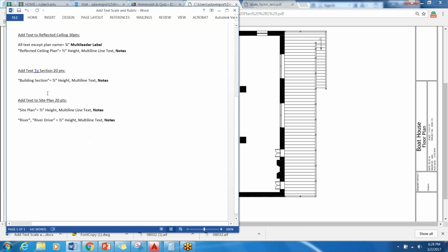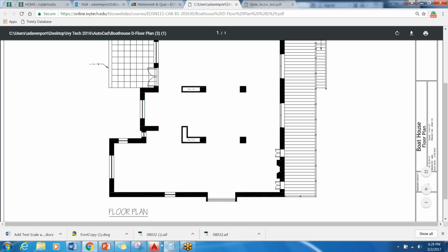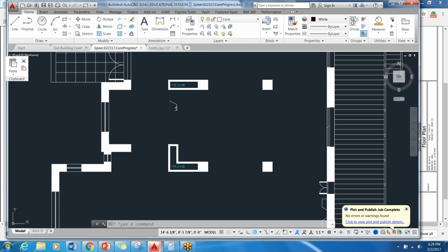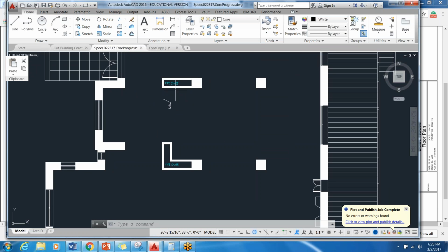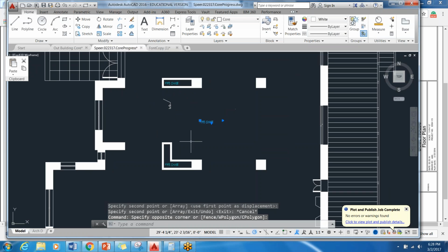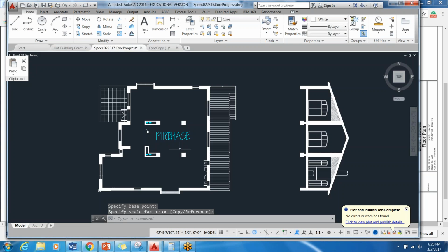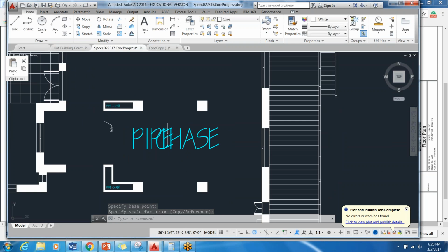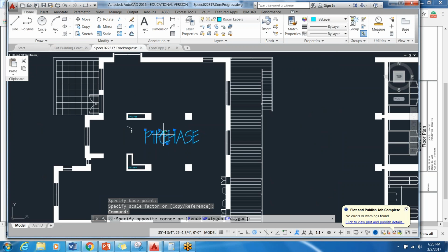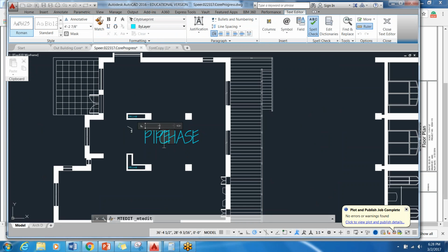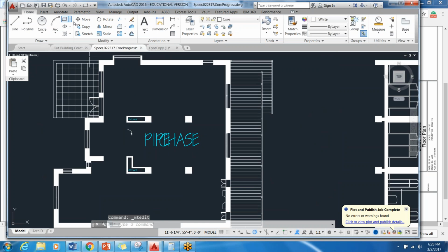So you can do them annotative, like I just showed, or you can do real basic people stuff, like going in to your drawing and figuring it out, you know, okay, well, you know what? I'm going to label the middle of my house for some reason. I'm just going to scale this text. And it needs to be this big because this is an important area. Okay, so we scaled it and that's great. If I double click on it and I want to know what that scale changed, it's 4'2" and 7/8, which is an unfortunate size, but that's okay.